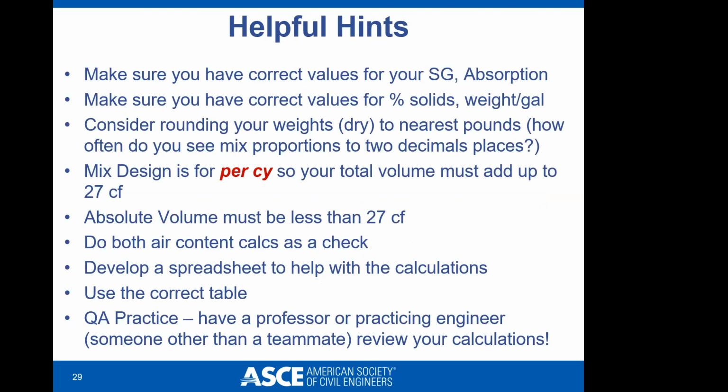So, some helpful hints. I know I'm going through this fairly quickly because we do want to get to the questions. We figure that most of you already have some aspect of concrete mix design, but we're going to be here to help you even if you have minimal experience. You want to make sure that you have the correct values for your specific gravity and absorption. Take a look at the data sheets provided to you by the manufacturers.